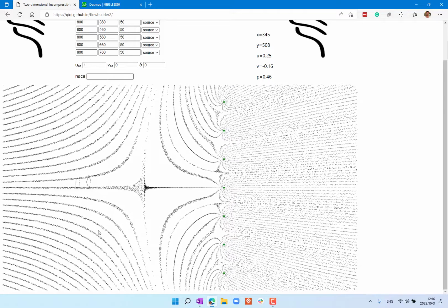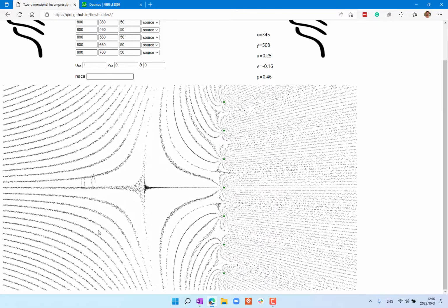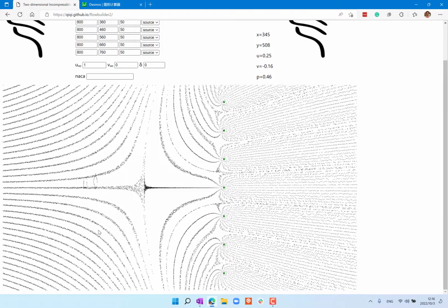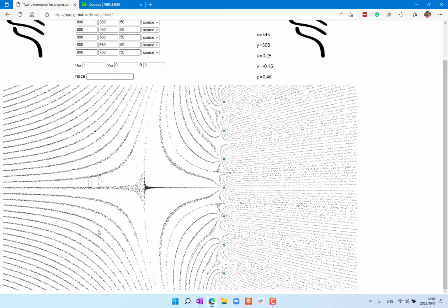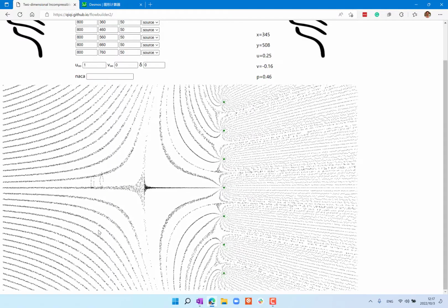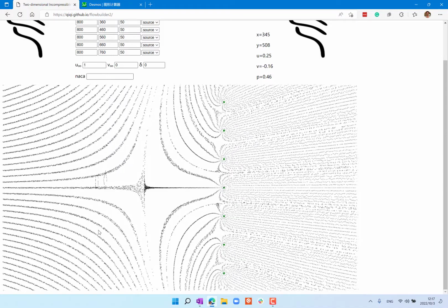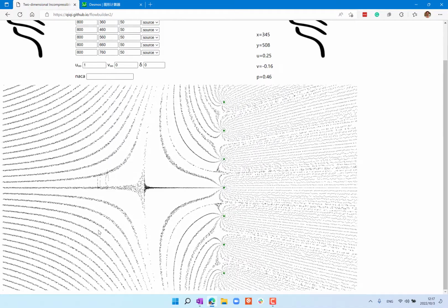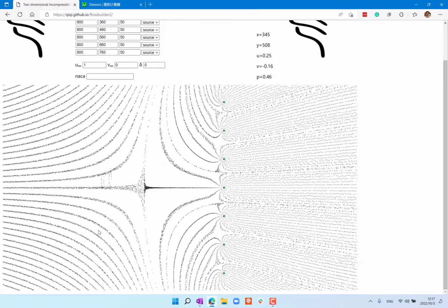That's not allowed in the irrotational flow field. So you can see as this diamond gets squeezed, the original edge that's pointing towards the positive x, positive y direction gets rotated in a counterclockwise direction, and the orthogonal edge gets rotated in a clockwise direction. So you get a thin diamond at the end.